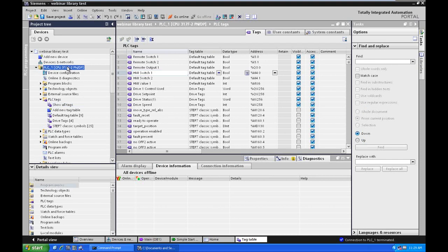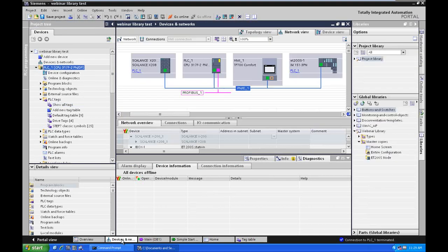So I wanted to touch base on system diagnostics, and what system diagnostics are going to allow us to do is pick up any event that occurs within this PLC's configuration. Every object you see here is a part of the PLC's configuration. That means I can have alarms coming from my Ethernet switch, since this is a managed switch, and from my I/O objects, which in this case is the one distributed I/O node.